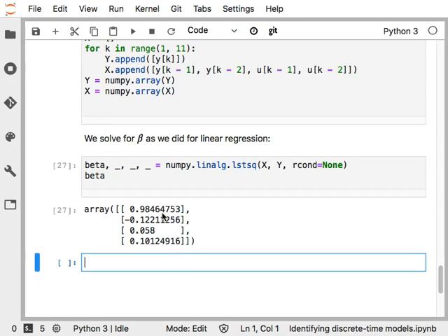Now, understand that this is amazing. No guessing, no weird side things like first needing to investigate the data. The only proviso is that we've sampled in a good way. If you're doing a step test of 5 hours and you've only sampled 2 seconds of values, but you've sampled 1,000 of them at 0.01 seconds, you're not going to capture the dynamics of the system, and the fit will fail, because you don't have enough data to cover the full spectrum of the behavior.